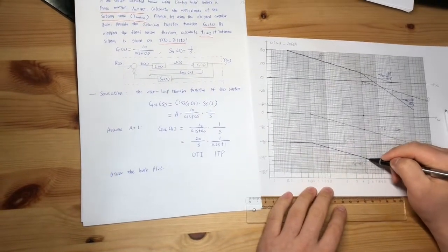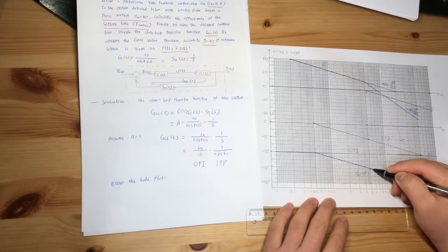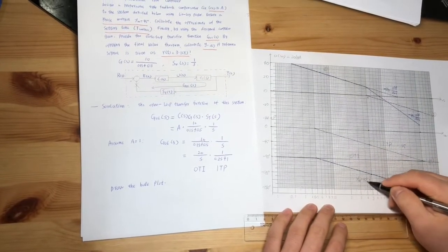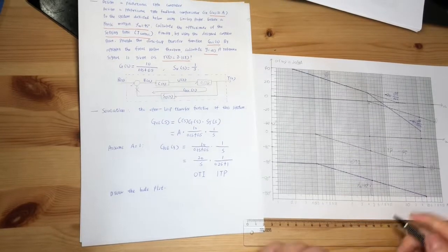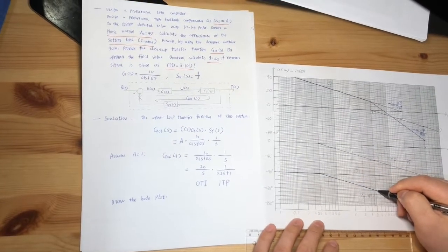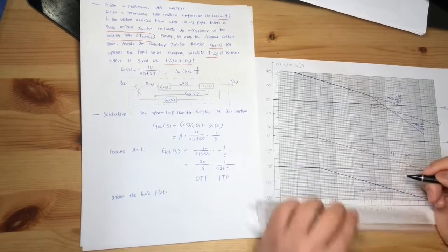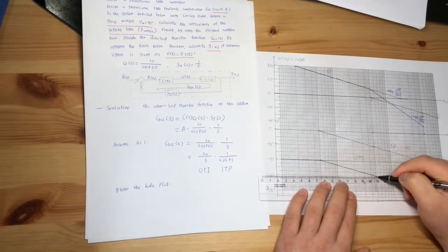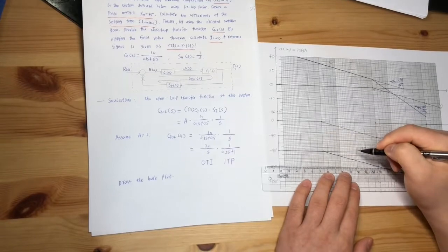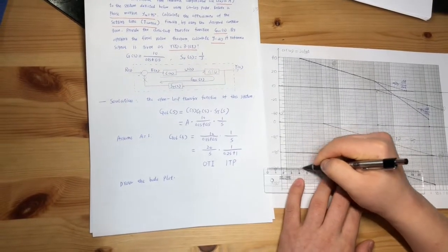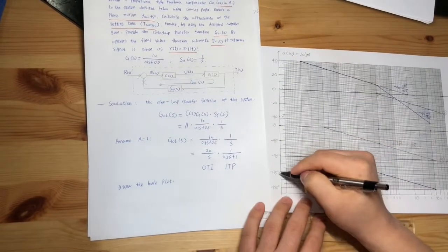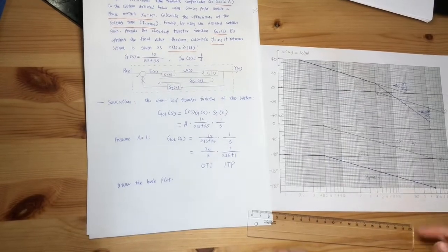And if we look at this diagram, with the phase margin equal to 45 degrees, we can find this point, accordingly the phase equal to minus 135.